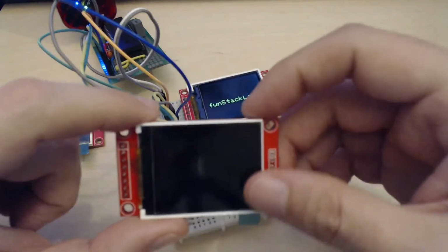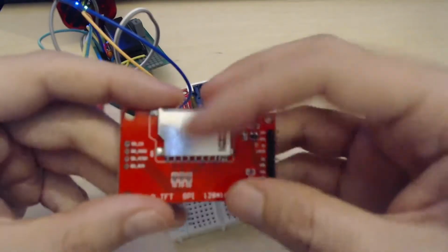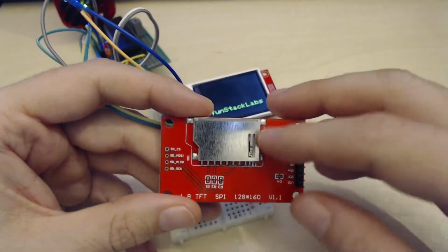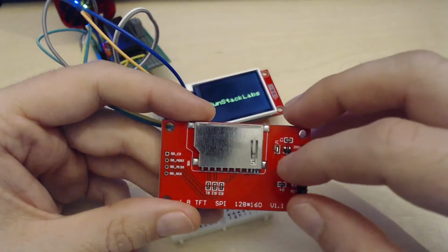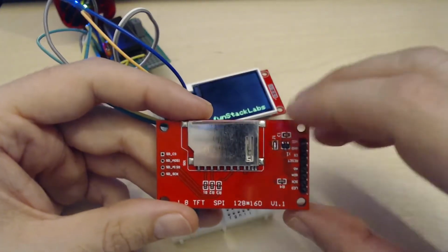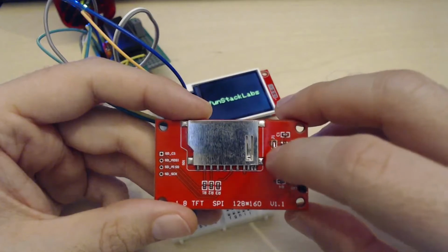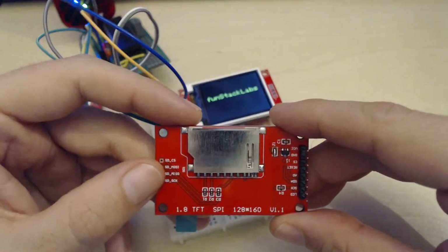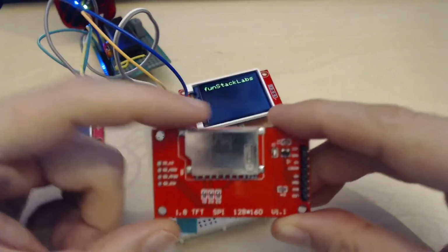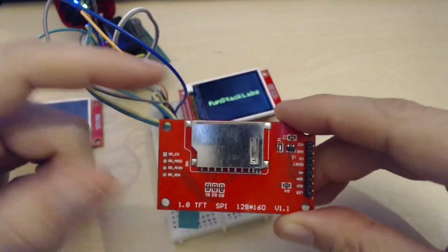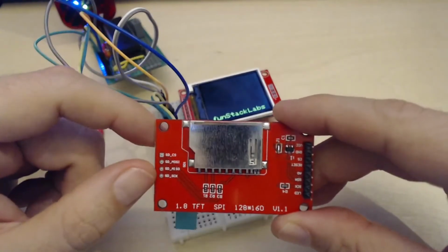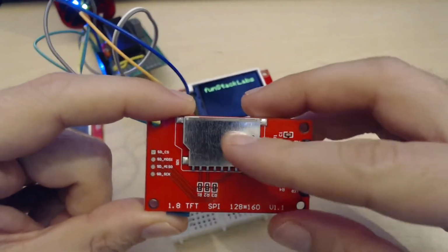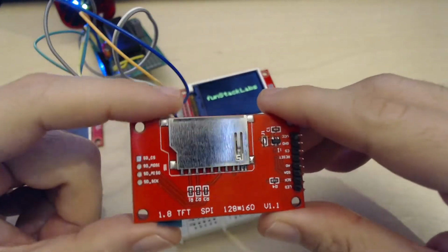On the front of it, we obviously have the LCD screen. We have an SD card holder here. It's not doing anything; it's just a breakout for an SD card. It's also connected to the internal regulator, so if you power this up with 5 volts, the 3.3 volt regulator will power your SD card as well, which is good. For communications with the SD card, all the pins are here. You can just pop in the SD card and hook it up to your microcontroller. You obviously need some sort of file system implementation, and the microcontroller does the heavy lifting, but it's a nice breakout for an SD card.